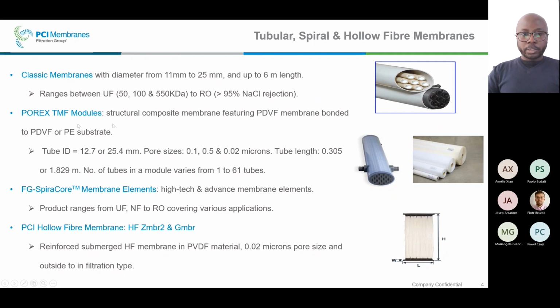But then when we're talking about the porous tubular polymeric filters, these are available in PVDF membrane, and they could be bonded to a PVDF or PE substrate. The porous TMF modules, as well as the classic membranes, as well as the previous tubular membrane that I've discussed about, they have a very open channel, which allows them to be suitable for high solid applications.